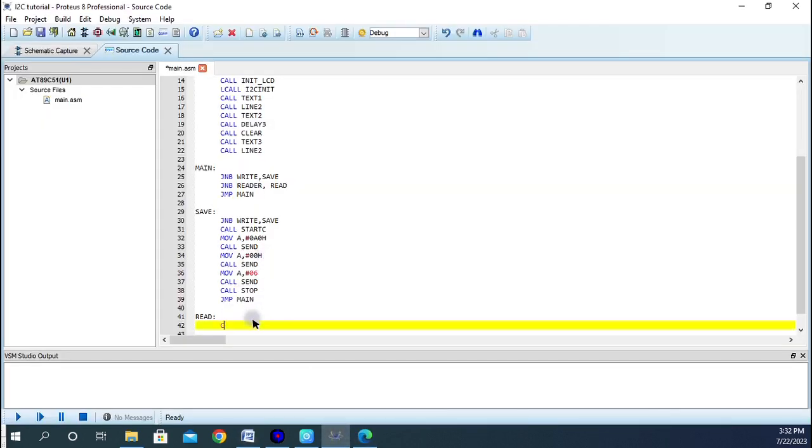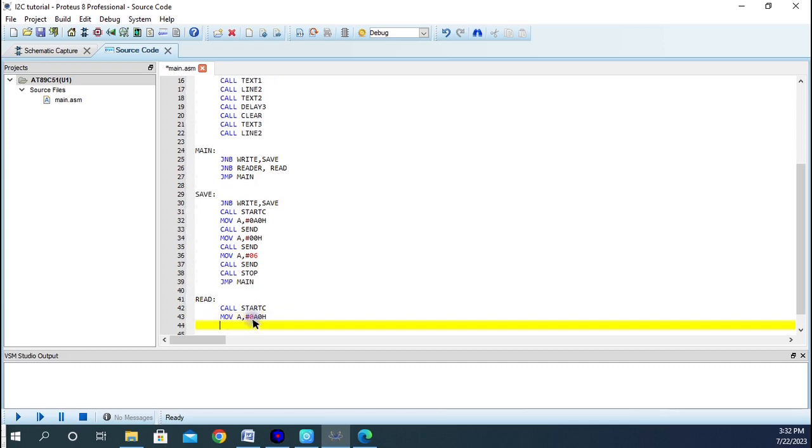We now start by first of all calling start condition. Our start condition, then we move to accumulator 0A0, that is the slave address that we want to communicate to. We send.